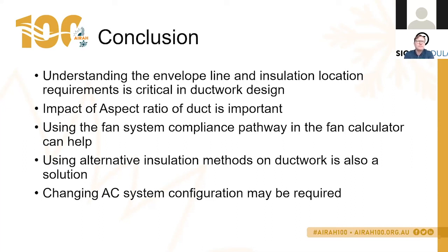And that ductwork leaks. You can't typically get any ductwork that doesn't leak some air out of it. So the riser would end up getting a tiny bit of air-conditioned air in it. If it's a fully internal riser that doesn't see any sunlight, it doesn't have any external load on it because it's adjacent to all conditioned spaces.